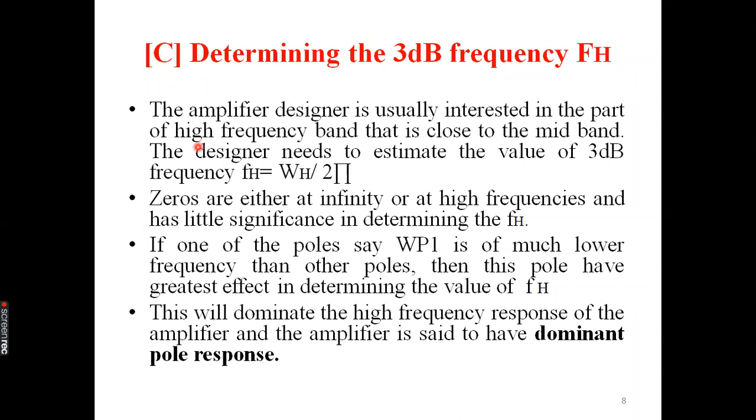So what is the speciality of estimating these cutoff frequencies? We should know what signal we have to give to this amplifier, and till what frequency this amplifier will amplify the given input. We can't give input signals of any frequencies. Why? Because the amplifier will respond only to a particular range. So if you are focusing on the out of range area, how will it work? It won't work. We will simply get some attenuated signals that are not at all desirable for us, right? So always we have to analyze the cutoff frequency of an amplifier. Based upon that only we will give the inputs.